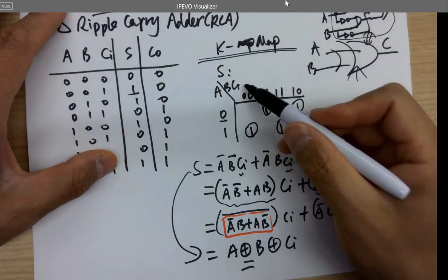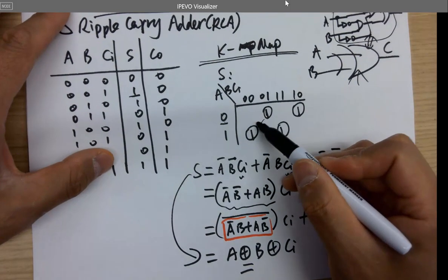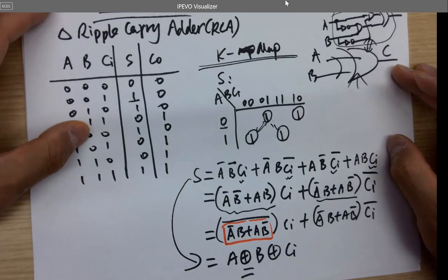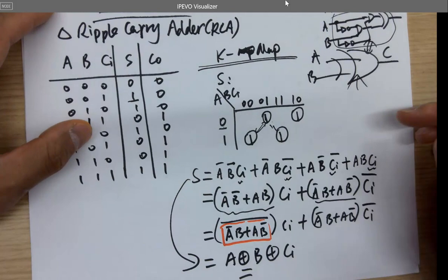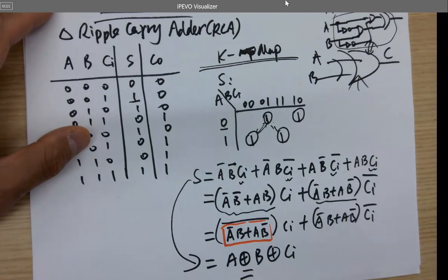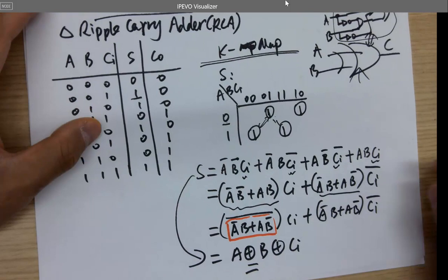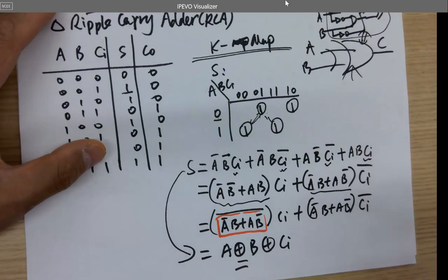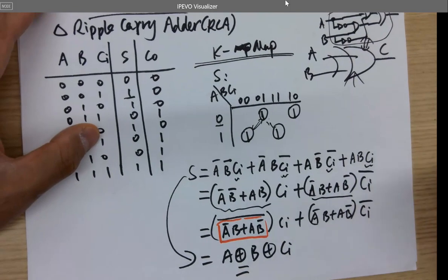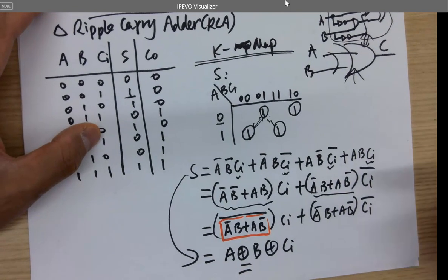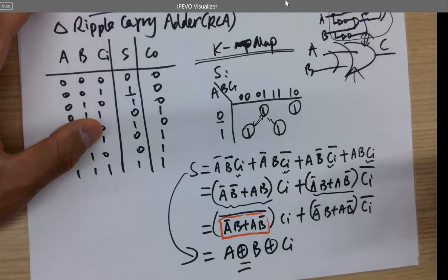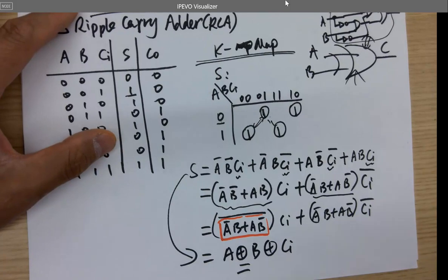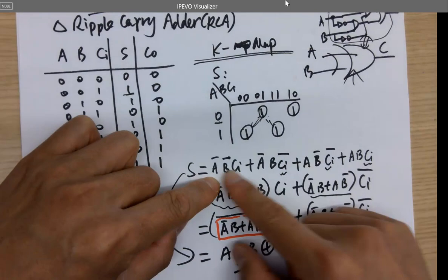The reason you cannot simplify is because of the nature here in the K-map. You don't have neighboring components that can combine and simplify it. They're all independent ones, right? But if you use the AOI logic instead of using the independent gates to directly build it through the logic, it may simplify the transistor level circuit a little bit, but won't significantly reduce the number of transistors from here to the AOI logic. You could even draw AOI logic from here, can you?